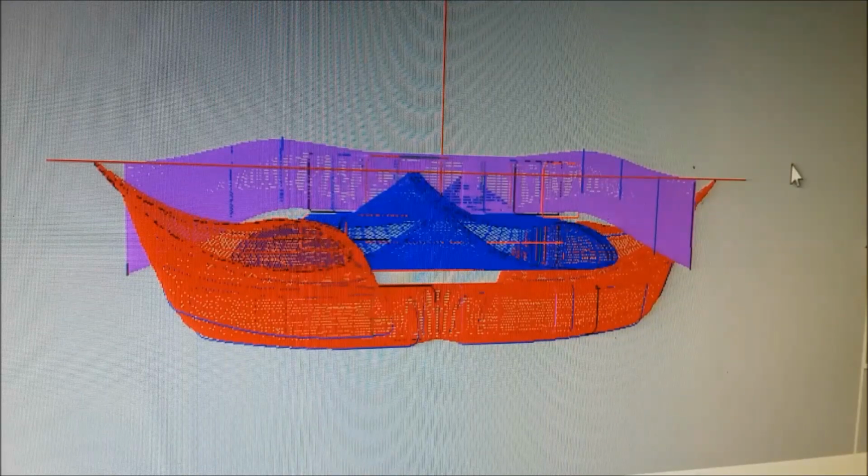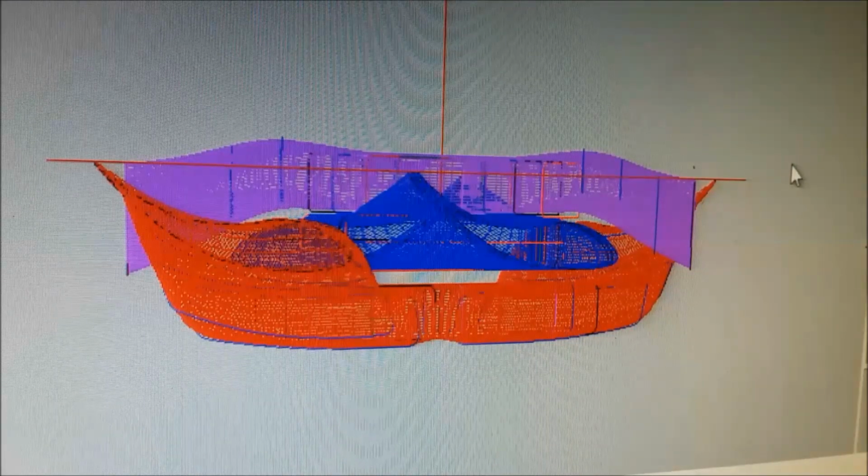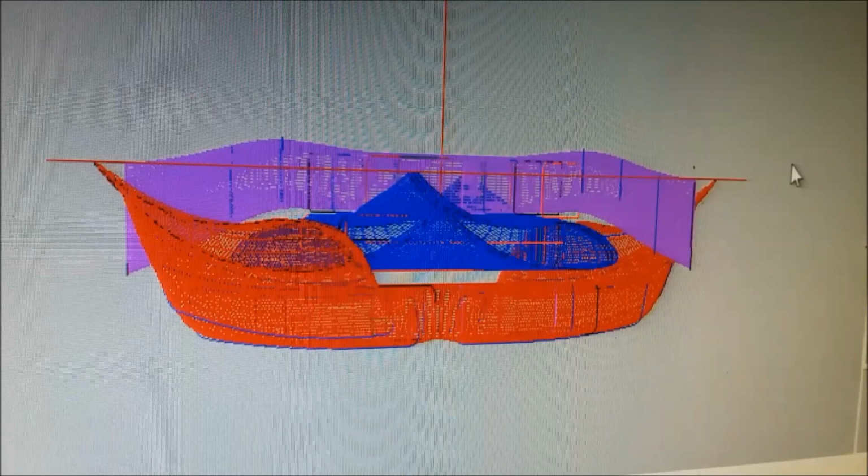So it bolts onto an arm that goes to the fan motor. There's 3 screws that hold the paddle blade onto that bracket. And what we do is put one washer for every 4 millimeters under the front screw until we get all up to the same plane. And then we turn them on, they don't shake anymore.